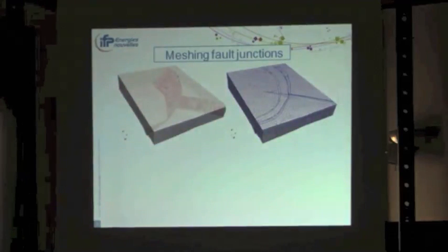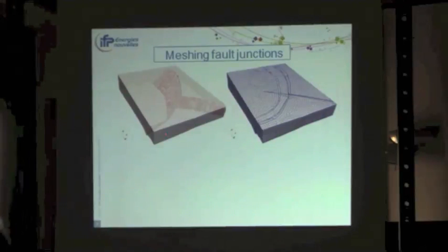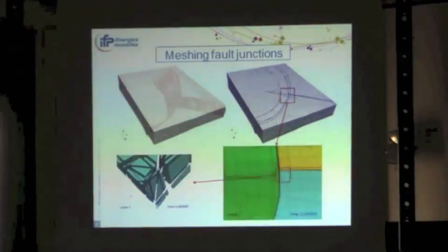The cracks in geomechanics constitute a major issue because the meshing of such geometries is very difficult for the meshing tools. Here we have a very simple basin model with one fracture junction, and if we zoom in on the area of the fracture, we observe elements that have a very bad aspect.